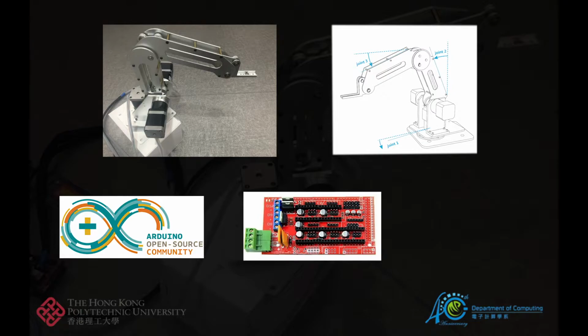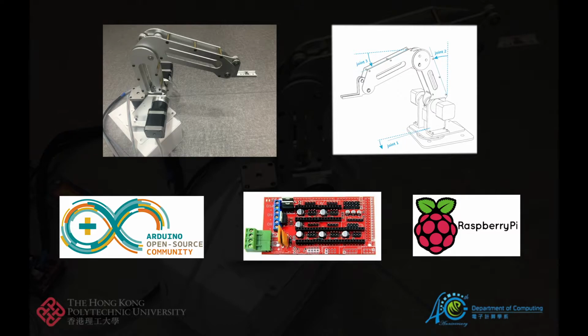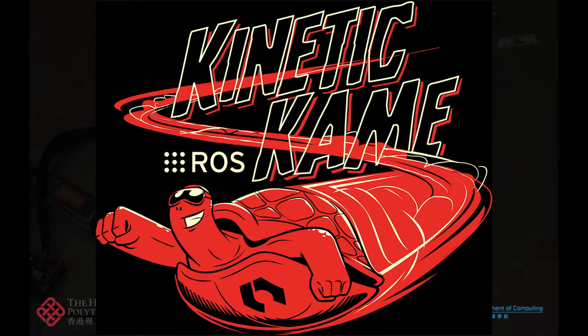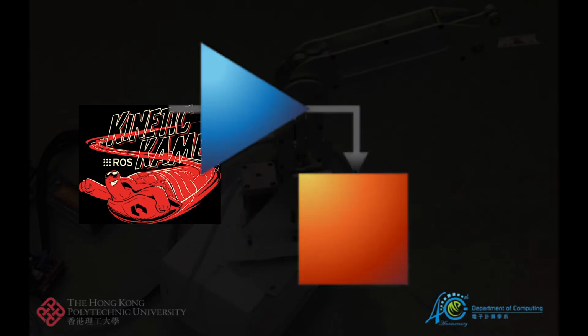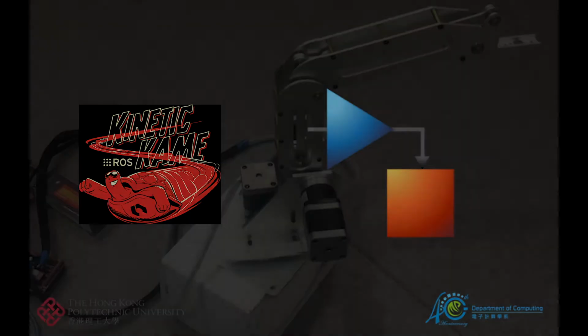Due to limited computational resources, Arduino cannot be used to implement complicated computer vision and machine learning algorithms. We decided to use Raspberry Pi to perform computationally intensive tasks, but still we need to write our code and communication protocol, which can be time-consuming, prone to errors, and hard to debug. To avoid these issues, we use ROS, a popular Robot Operating System, for the communication layer, and Simulink for algorithm implementation, since it provides extensive support for ROS through the Robotics Toolbox, and for Arduino and Raspberry Pi through hardware support packages.